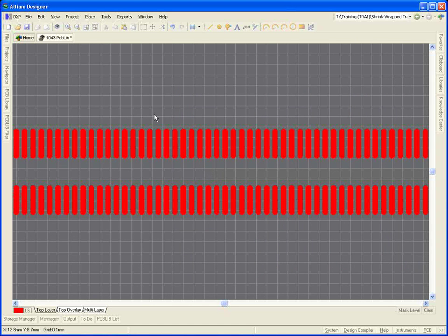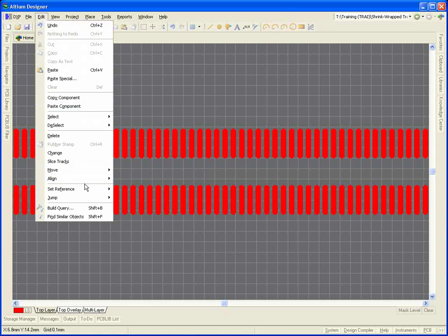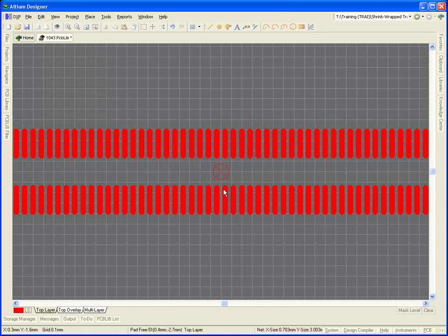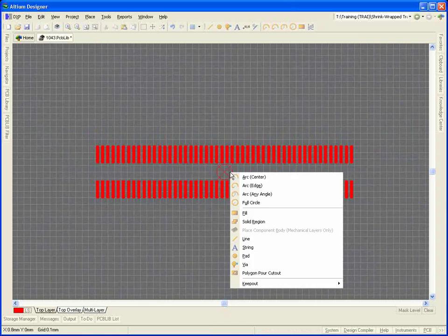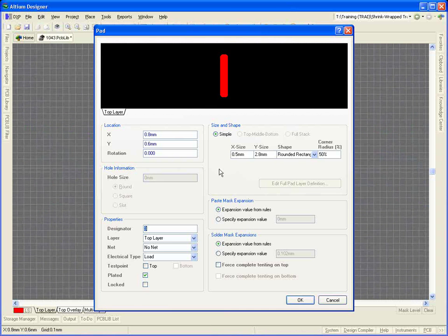Since the dimensions are referenced from the geometric center of the component, you can set that as the reference point for your new footprint using the Center Menu command. Place the 2 mounting pads for the right-hand end first. Place, Pad, and then press Tab to configure the pad. 0 is a good designator for these 4 mounting holes, and they'll be multi-layer pads. Set the hole size to 0.8, the pad shape to round, and the diameter to 1 mm.